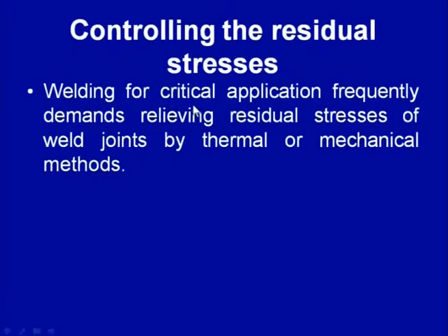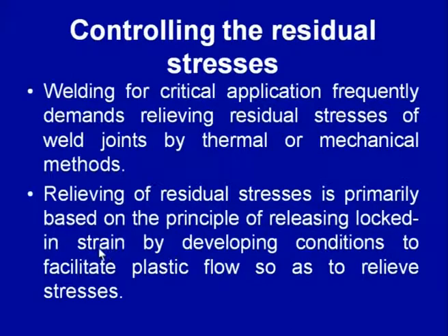Since the presence of residual stresses is not favorable for the performance of the component, especially from the mechanical performance point of view, the weld joints which are to be used for critical applications must be relieved from the residual stresses, and this relieving is mostly done using mechanical and thermal methods. The relieving of residual stresses is primarily based on the principle of releasing the locked in strain by developing conditions that can facilitate plastic flow.